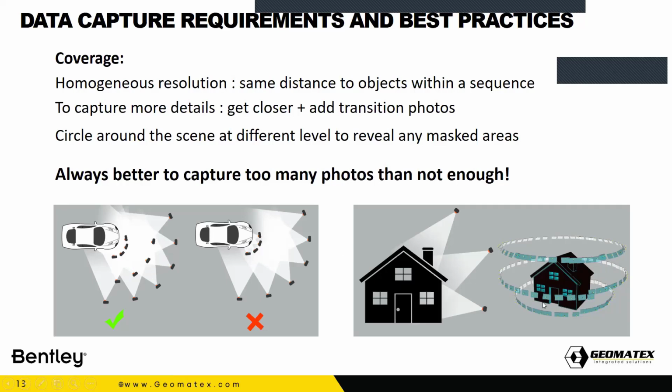And also, if you are having images from different perspectives, which means that I'm using my mobile camera or my normal camera or my professional camera from the ground, and then I decided to take oblique imagery or nadir imagery from the top with my drone, please make sure to have another run to be able to fuse this plane with this plane together through this overlapping oblique imagery. So in this case, you are helping the software to match pictures together and also to keep the accuracy of the model itself.